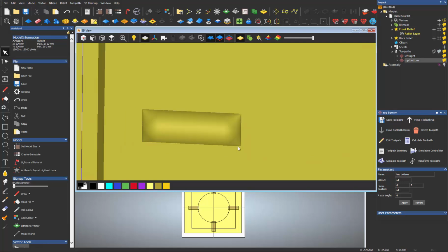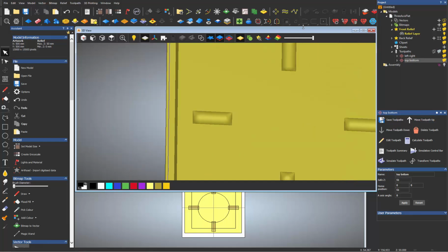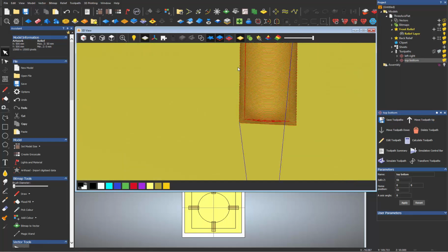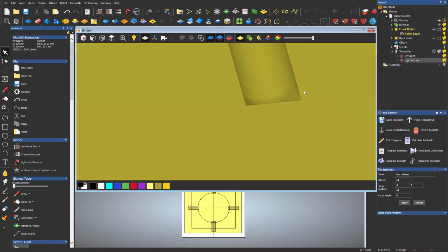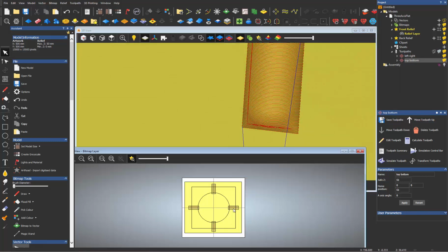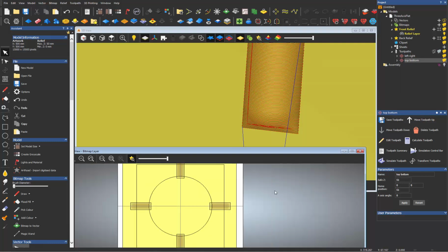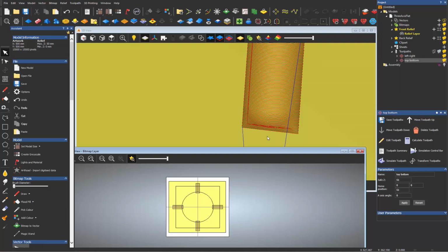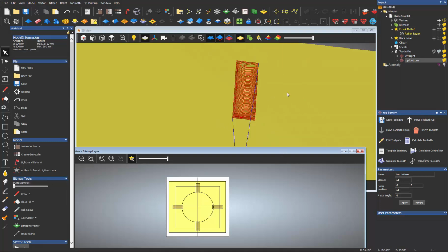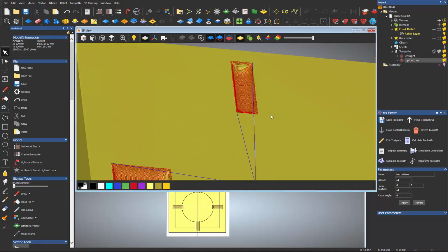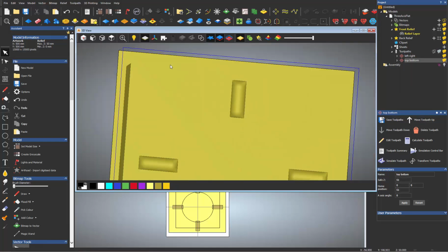I'm just going to show how I got these to go one direction, and then if we look up here, I've got these to go another direction. And then another thing that you'll notice is this is the circle. I have this toolpath extending into that circle, but it's not bored out yet. And I have it going past the actual material. And the reason for that is anytime you create a toolpath with a ball nose, and let me just simulate this really quick.